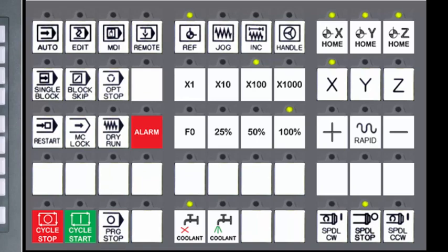For example, cycle start is the button that the operator presses when they want to execute the selected part program. FANUC cannot predict all the situations that must be checked on a particular machine tool to determine if it's safe to allow the cycle to begin. There will be door interlocks, operating pressures, machine mechanism positions, and other things to check.